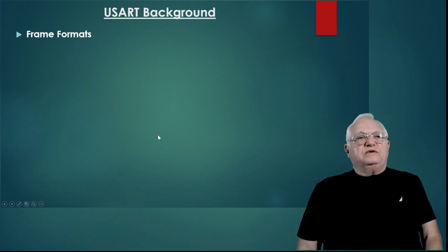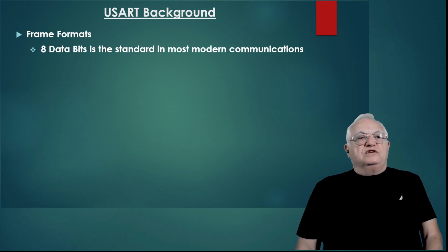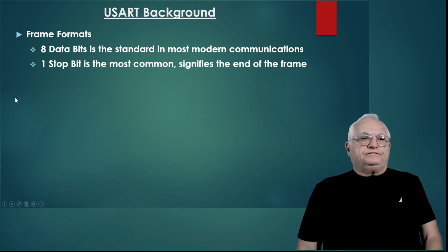So let's get a little bit deeper into the data format. Let's start with the frame formats. So 8 bits is the standard in most modern communications. It's usually 8 bits that everybody uses. Next, 1 stop bit is the most common, which signifies the end of the frame.